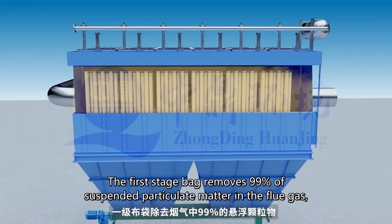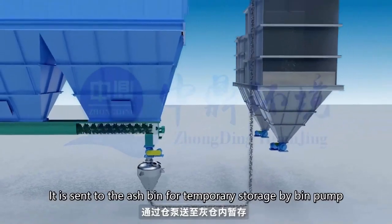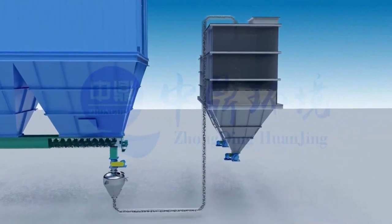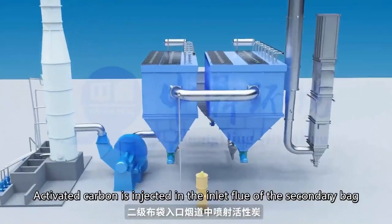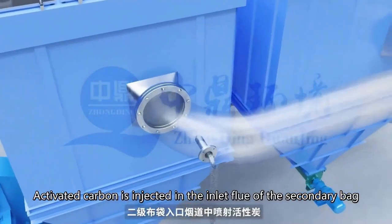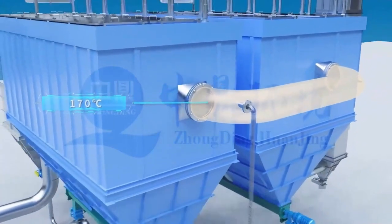The first stage of the bag filter eliminates 99% of suspended particles in the flue gas. The dust collected here is generally recognized as general solid waste, sent to the ash warehouse through the pump for temporary storage, and can be utilized in making bricks and cement. At the entrance of the secondary bag filter, activated carbon is added to the flue gas to adsorb trace heavy metals and dioxins.